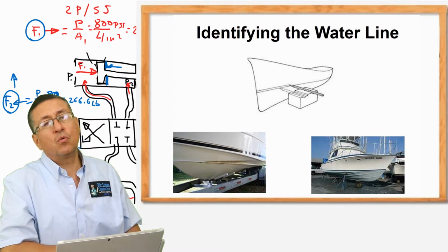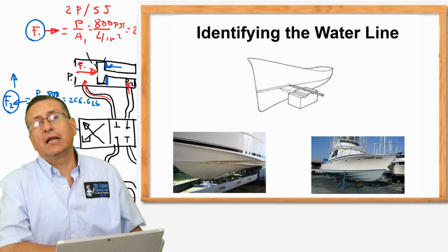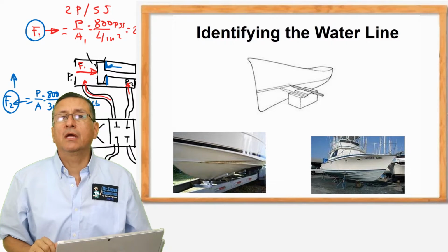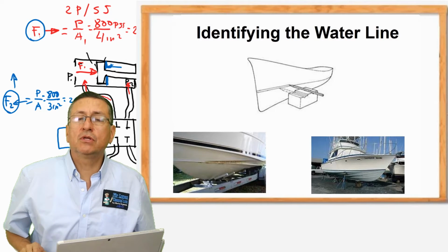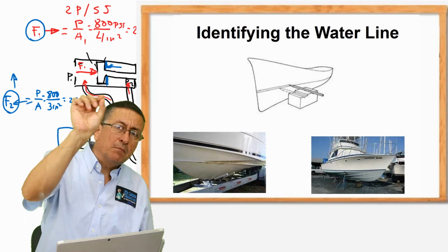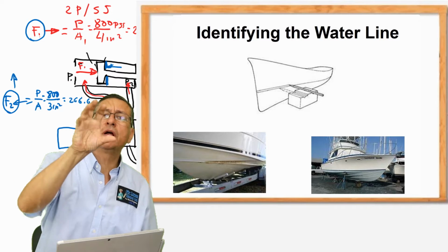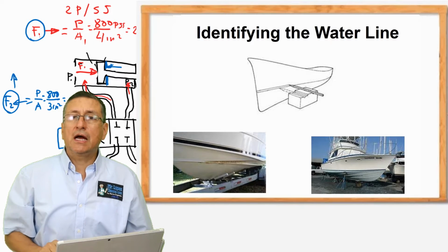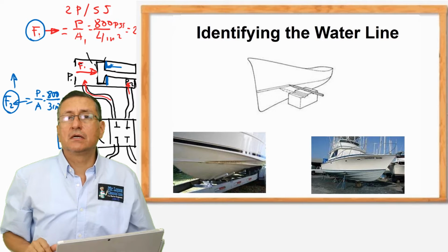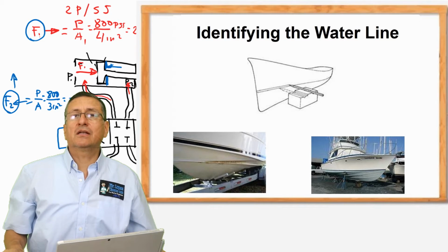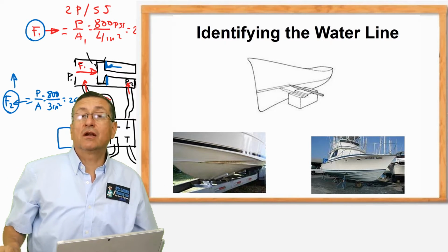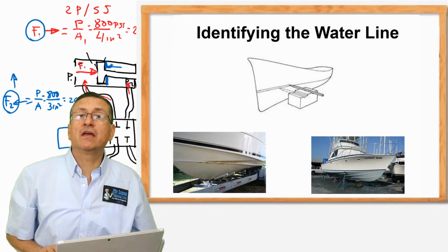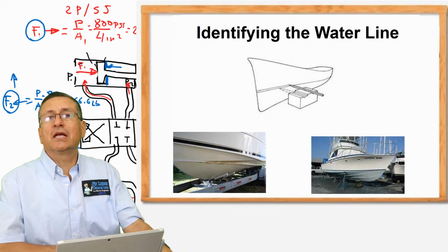Check outside of the boat where the water line is located, and verify approximately where that hole should be located. I recommend, if you have the boat in a marina, mark it provisionally with a pencil where the hole should be located according to your preference, and ask other technicians, especially technicians dedicated to installing hydraulic systems, what their opinion is about the tunnel at that point.